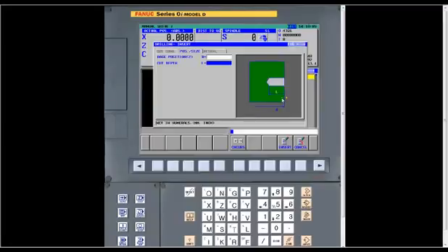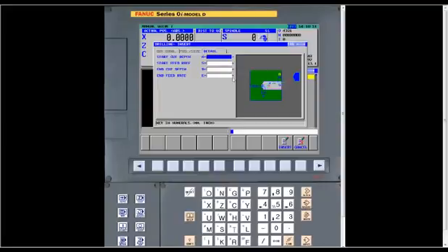So that's very simple. Then it also has detail data. And again, all four of these have asterisks next to them, so you do not always have to enter that information. But what this detail is, say you had a very large drill and you wanted to start it out at a much slower feed rate than what you would actually want once it got fully engaged. That's what this is for, where you can start out at a slower feed rate and then increasingly make it faster. So that's what a drill cycle looks like.